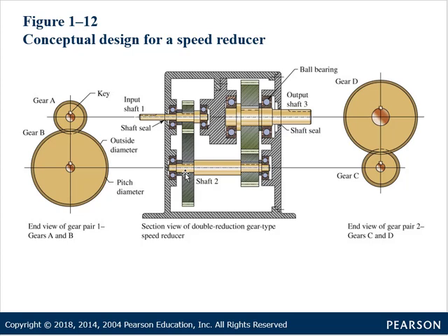Okay, so when you've got shafts turning gears, those gears working on each other to transmit torque impart forces into the gears. Those forces in the gears put forces into the shafts, and the shafts' forces are taken up by the bearing locations, the reactions at the bearings. So it really is important to consider all of the different facets of the design and all of the different items that each part in the design touches to know what the forces are and what the consequences are of the design.